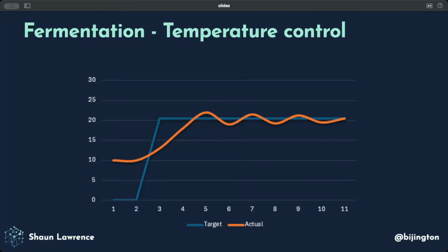And then once we start to drop down the curve, when we reach the target temperature as we're dropping, there will be time for the heater element to kick in and actually start affecting the temperature of the brew again. Therefore, it's not very efficient because you'll end up with this temperature oscillation. So let's take a look at how we can potentially solve this.